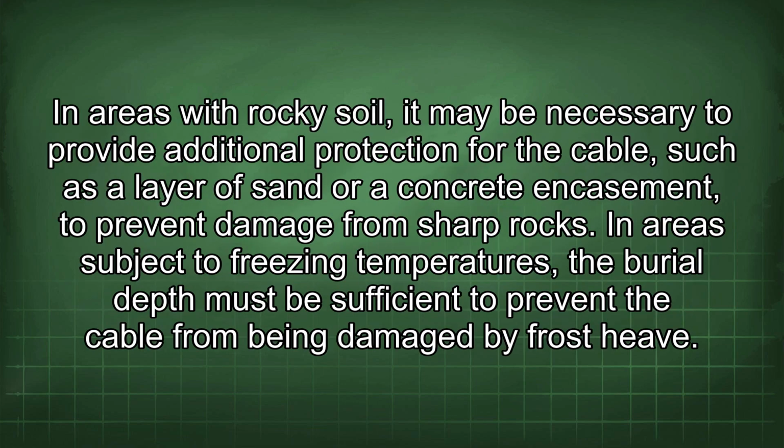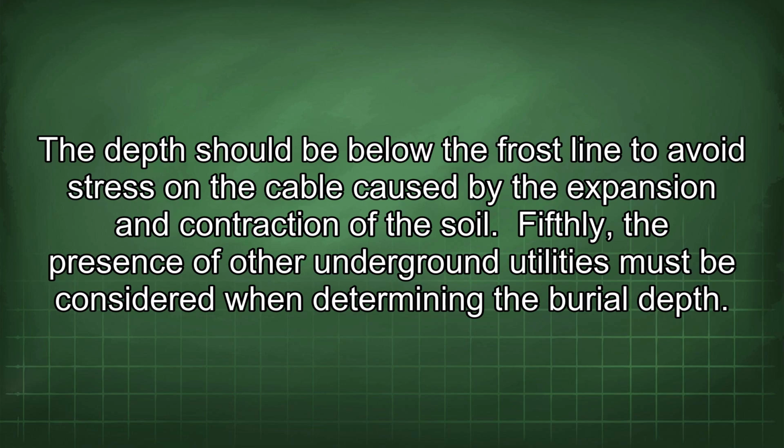Fourthly, soil conditions and environmental factors play a crucial role in determining the appropriate burial depth. In areas with rocky soil, it may be necessary to provide additional protection for the cable, such as a layer of sand or a concrete encasement, to prevent damage from sharp rocks. In areas subject to freezing temperatures, the burial depth must be sufficient to prevent the cable from being damaged by frost heave. The depth should be below the frost line to avoid stress on the cable caused by the expansion and contraction of the soil.